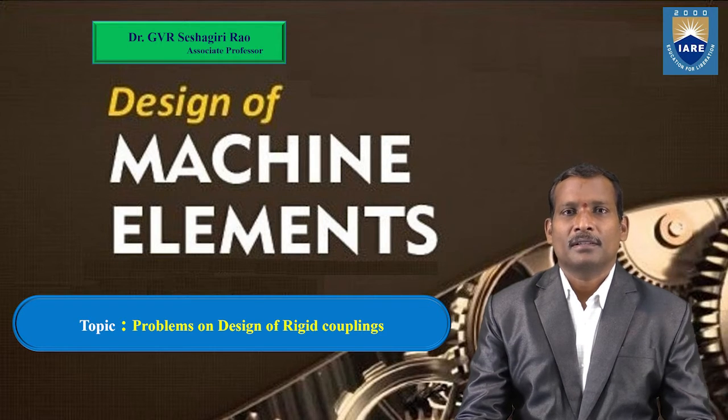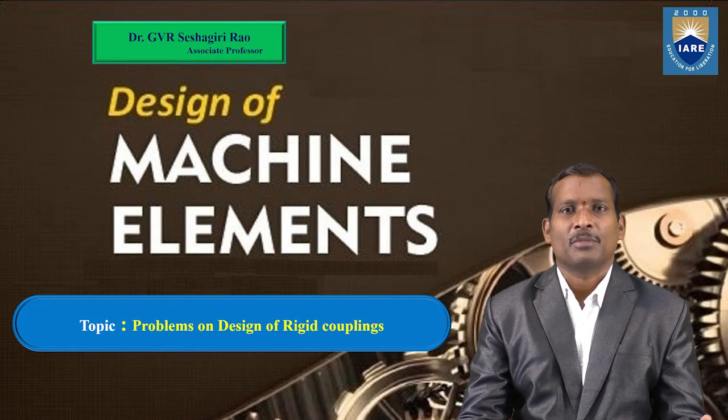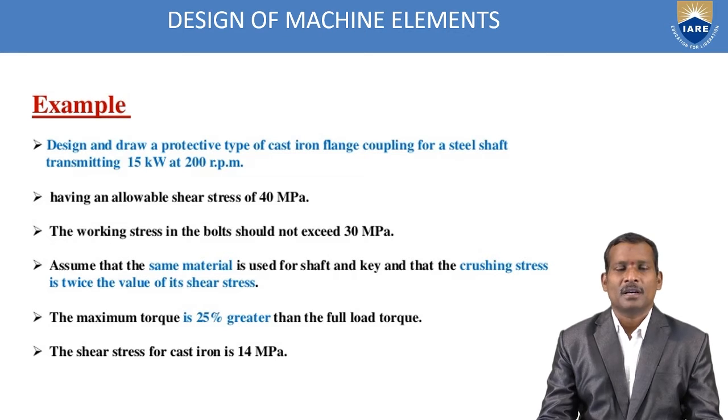In the previous session, we learned the design procedure of a flange coupling. So in this session, we will see problems on flange couplings, how to solve a flange coupling problem. Take this example: design and draw a protective type cast iron flange coupling for a steel shaft transmitting 15 kilowatts at 200 rpm. The given type of coupling is a protective type cast iron flange coupling.